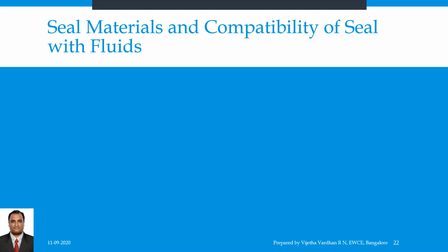Natural rubber materials cannot be used in hydraulic systems as they tend to swell and perish in the presence of oil. The synthetic rubbers, also called elastomers, are for the most part compatible with the oil. Elastomers can be made in various compositions to meet various operating conditions. The different elastomers used in sealing material: the first one is called neoprene. Neoprene is one of the earliest elastomers used in sealing material, a tough material with a limited temperature range up to 65 degrees centigrade, still used in most systems.